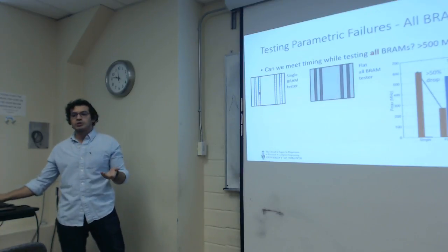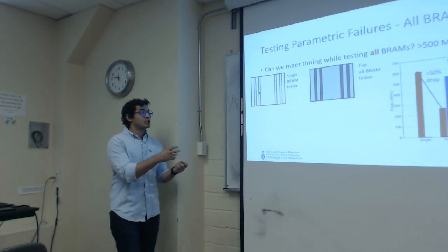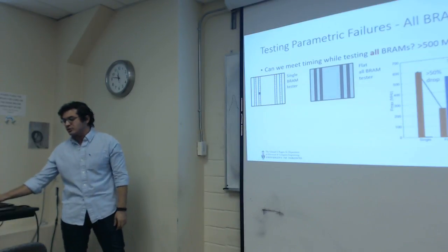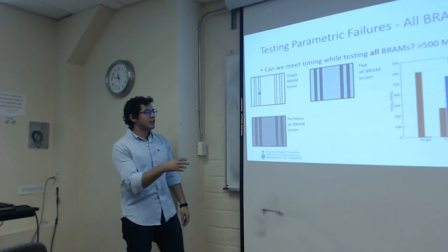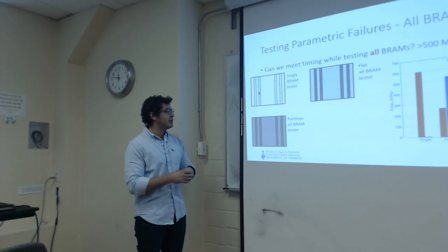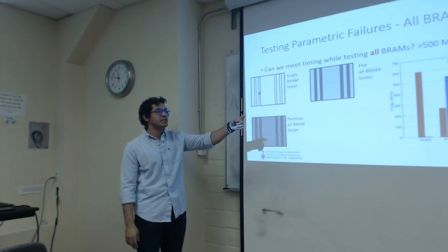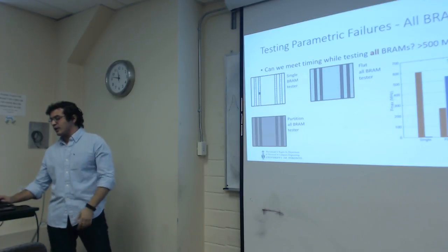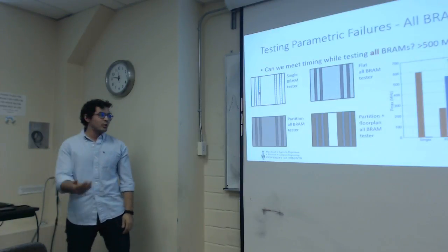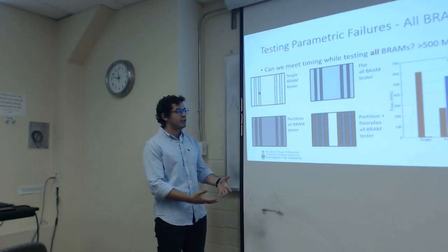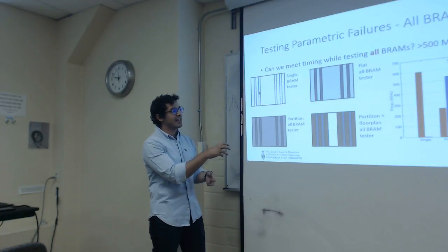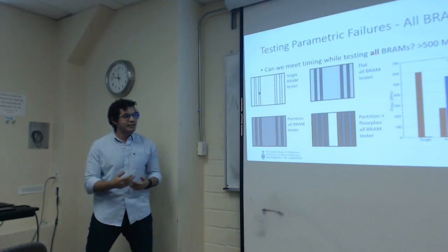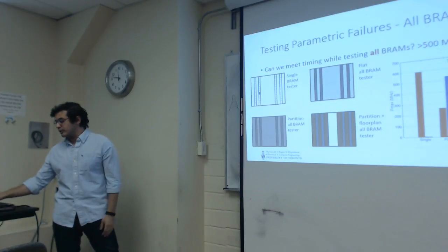We noticed that Quartus was trying to optimize to share some logic between the testers, but because we know that they're independent, we partitioned them such that Quartus doesn't do this optimization, and we actually got some frequency and logic utilization increase, but still nowhere near what we want. We went one step further and we floorplanned our design manually. We know exactly what we want. So we got another frequency bump, but again, it wasn't anywhere close to what we want.